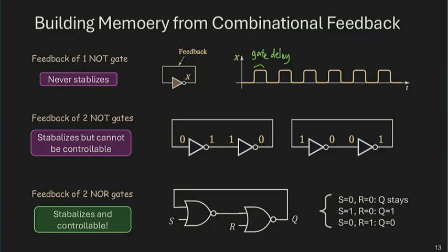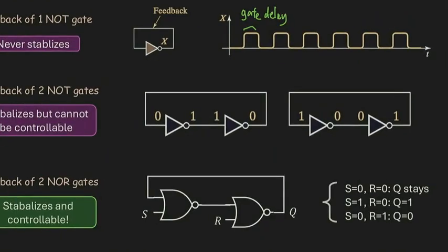To address that problem, we can put down two NOR gates, again, back to back, and control them with two different input signals. And then we'll see what will happen in this circuit is that, let's say if you put down a 0 and 1 over here. 0 will directly control the NOR gate output to a 1. 1, 1 gives you a 0. 0 cycles back, and then gives you an output of the NOR gate, a 1.